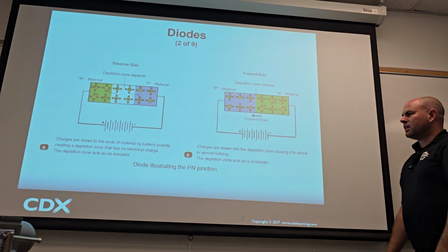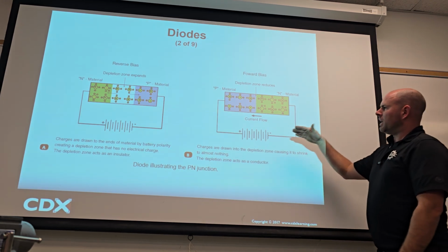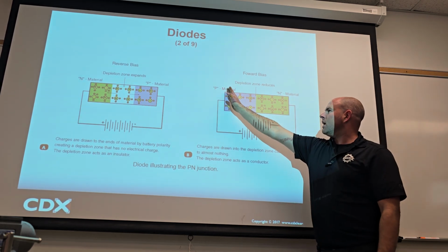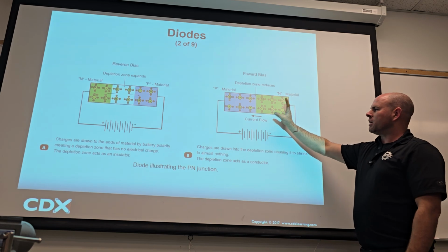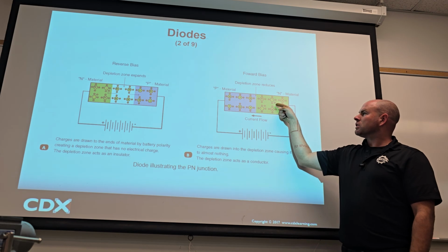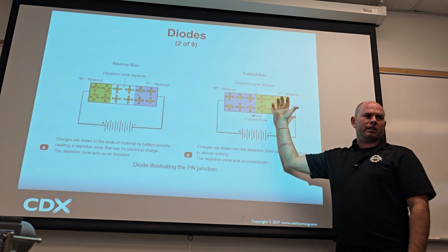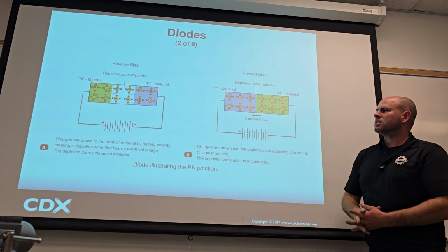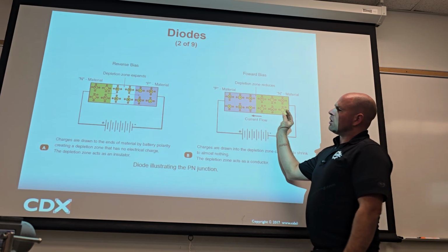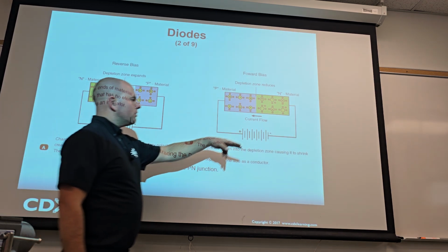And then in the intricate details, let's just say in this one, current flow is supposed to go this way. They'll actually arrange it so it's P on the left and N on the right. But if you were to accidentally flip it, can you see it wouldn't allow it to go this way. It can flow from N to P, but it can't flow from P to N. So that's why the direction we face this is so critical. It's also showing that when it tries to flow, this one's going to be blocked and this one's going to flow.